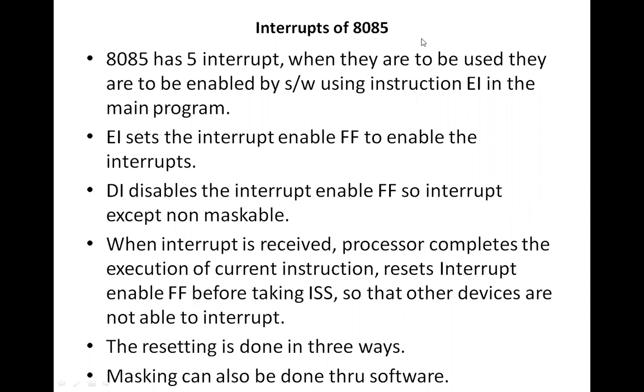Now this resetting of the interrupt enable flip-flop can be done in 3 ways. The first way is by including a DI instruction within the program.